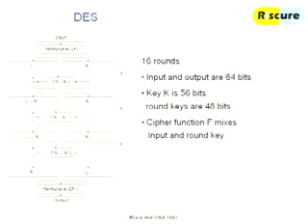Now, I'm not sure if everyone here is a crypto guru, so I just want to try and get across the main message, which is this. Like I said, input correlation is easy. You have the input, you have the measurement, you just correlate and you find the peaks where the input is used. With the key, you can't do that, because that's the secret. So what you want to do is pre-compute to some point in the algorithm where you know the key is being used, but maybe just barely, and then try to correlate with that.